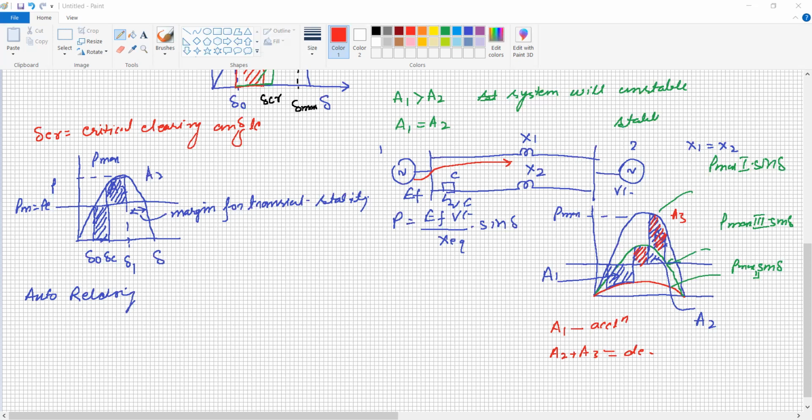The power reduces to a small value. And once the fault is cleared, meaning one of the transmission line circuit breakers opens, the system is going to transmit the power by a single transmission line. Therefore, the power transmission capacity will be smaller. So it is the post-fault condition.